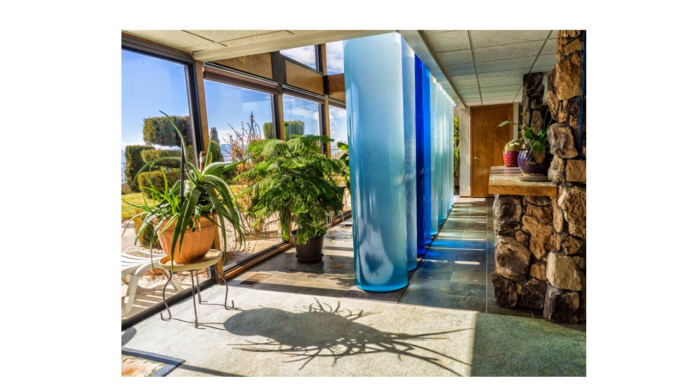So when I said large tanks of water, you probably thought like who would have large tanks of water in their home. This is a really cool way to do it in a very artistic and nice looking way. So what these people have is again the passive solar. This is south facing and it's going to probably be shaded during the summer. All of this water, all of this stone on the ground, all of the stone of this fireplace or whatever it is, is all going to absorb heat during the day and then slowly radiate it out at night.